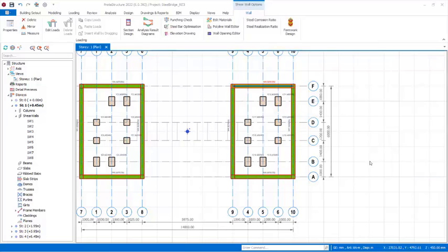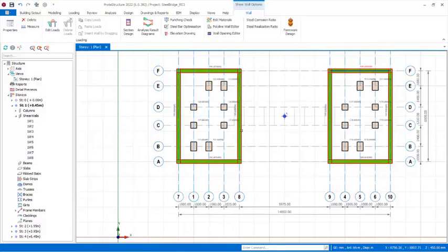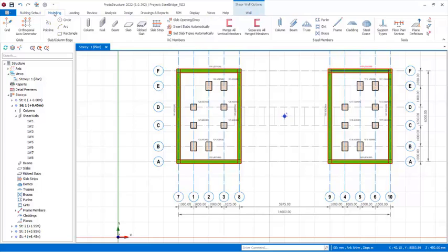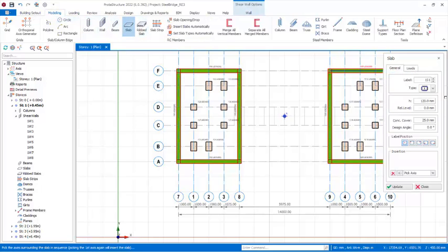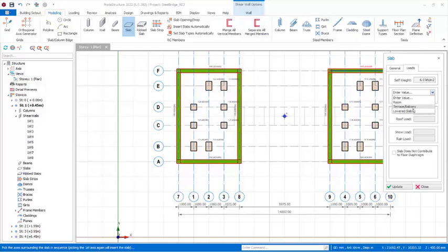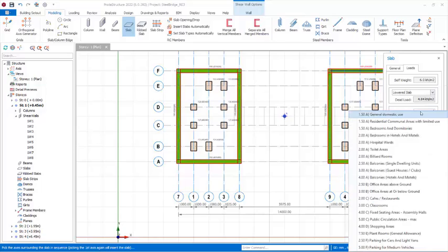Okay, so having placed this successfully, you need to also have an additional extension of the slab. So we will proceed to the slab provisions right there. Click on the slab, and then you come over to the thickness of the slab, we maintain 250. All right, and then get over to these provisions. We use lowered slab, and then we use 7.5.